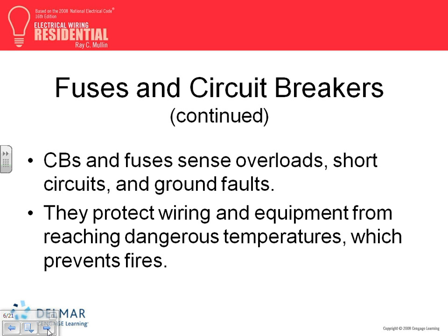We mentioned this one, guys. Both fuses and circuit breakers are listed for overload, short circuit, and ground fault. And all these are fancy names for different levels of current. The overload is the lowest level of current. The ground fault is the second, and the highest is the short circuit. Different levels, the same current.